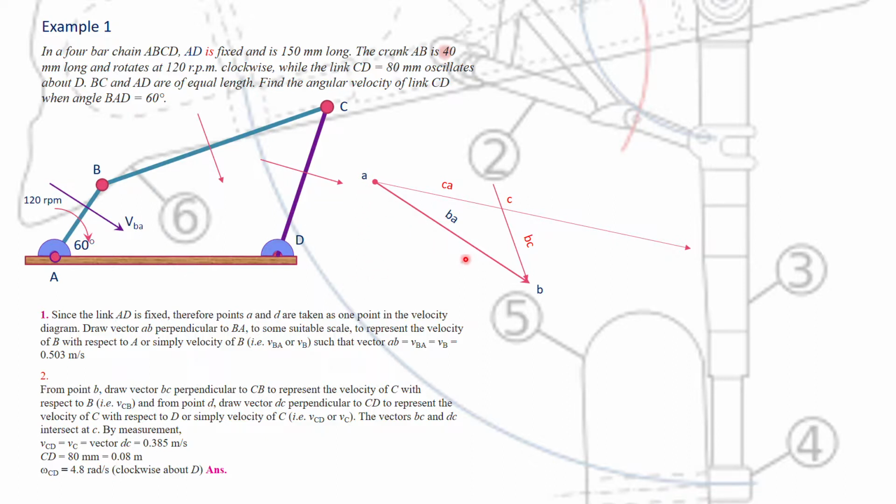So once you got AB, the next thing is this here. This is referring to BC. From here, you have already got B, right? So you need to draw a line on point B. You don't know the arrow direction yet. You need to draw a line on point B which is parallel to this component here. You draw across point B, until below point B in this case.